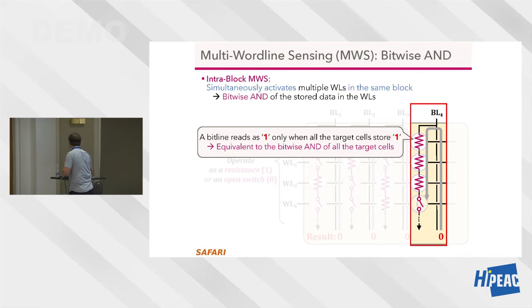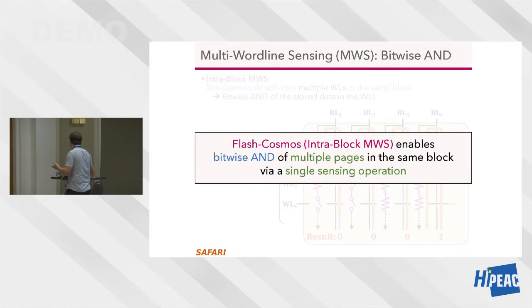So if any of these is a 0, if any of these is a 1, you get a 1 at the end. All of these things that are connected to that wired OR need to be a 0 so that you get a 0 at the end. And this is an OR function in the end. Okay, so that's how you get the OR function.